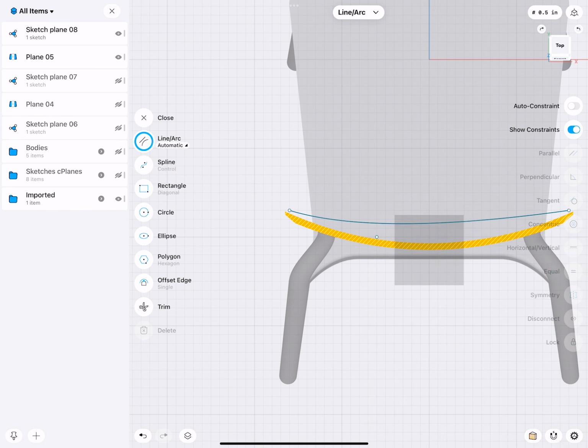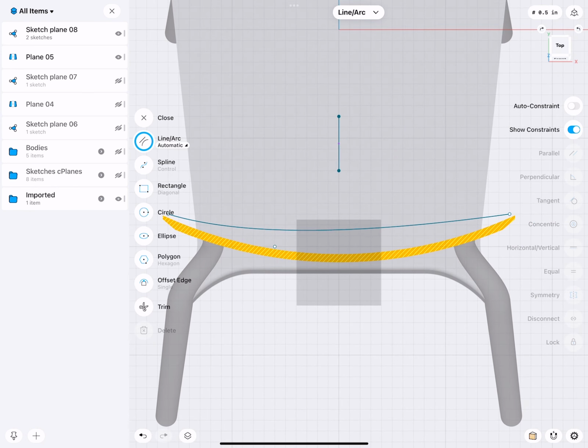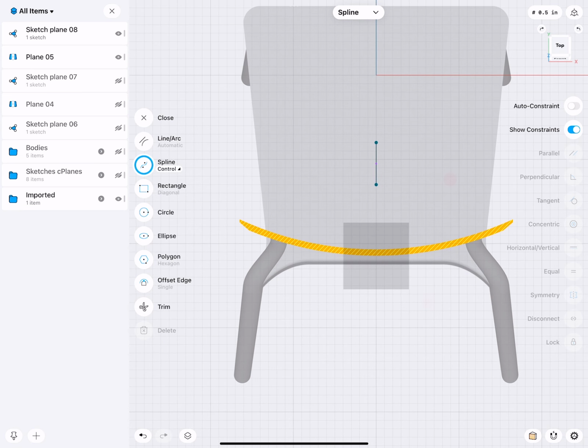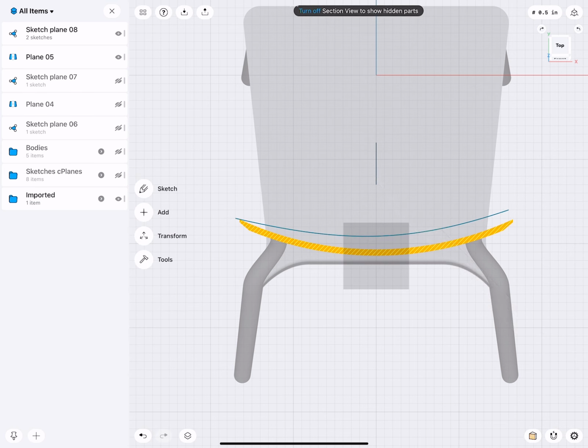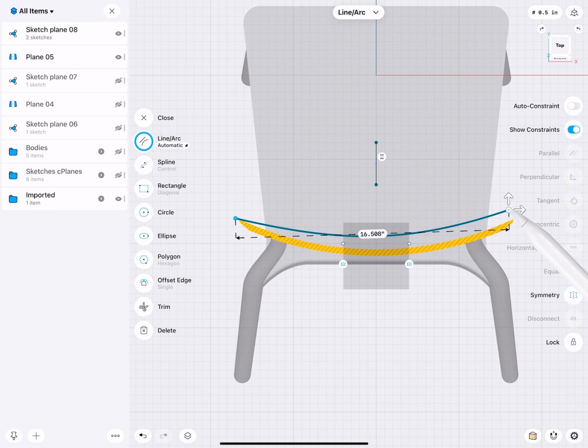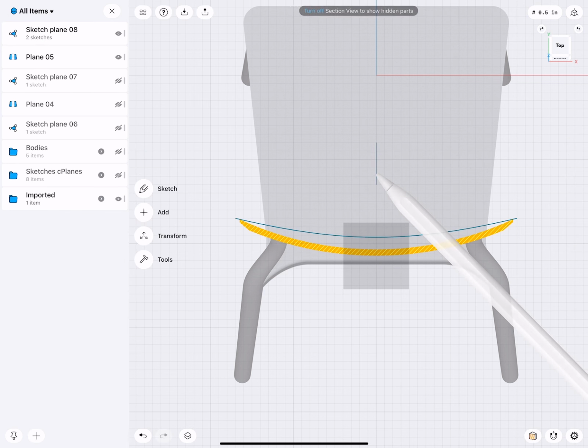Grid is turned on. I will create myself somewhere a nice line. That's a mirror line or symmetry line. Lock it. And I forgot to add one extra point. So number 1, 2, and 3. There. Then I can select these 2 points. Symmetry, this line. Go back. First point, last point. Symmetry here.